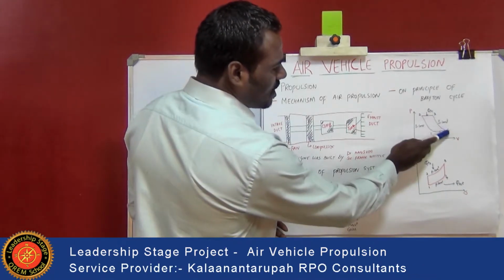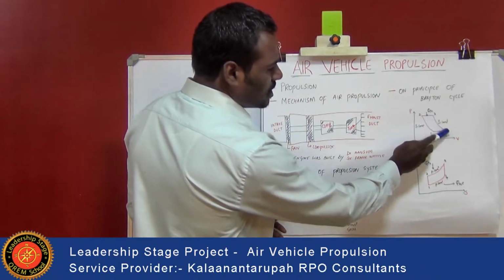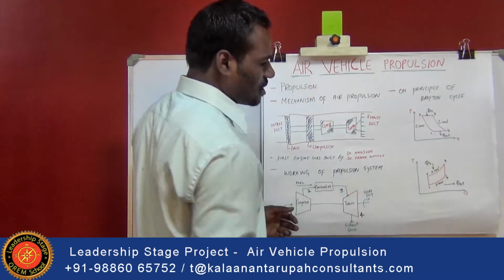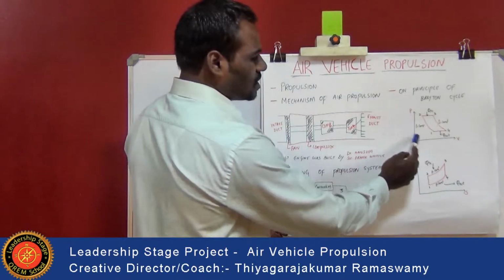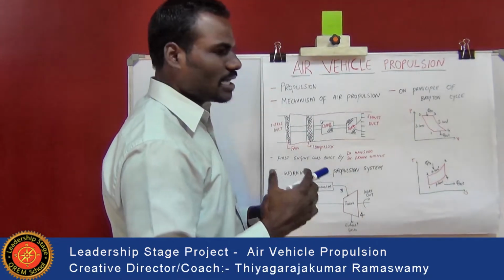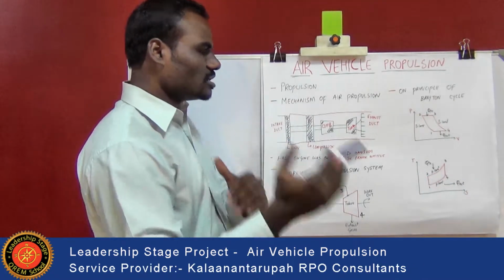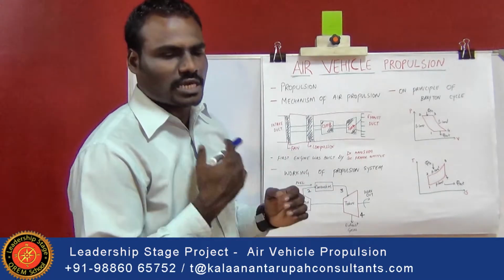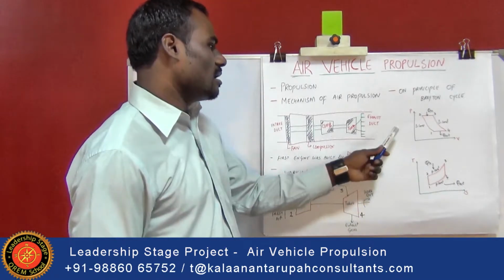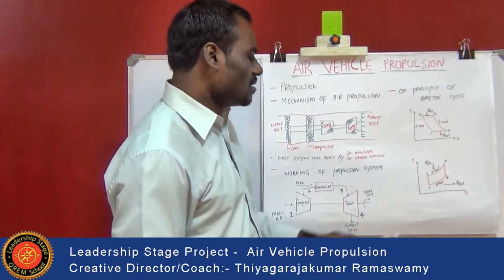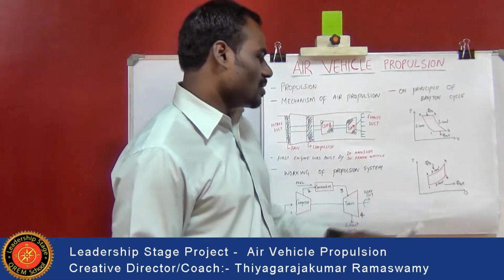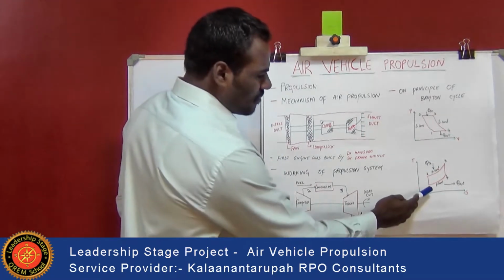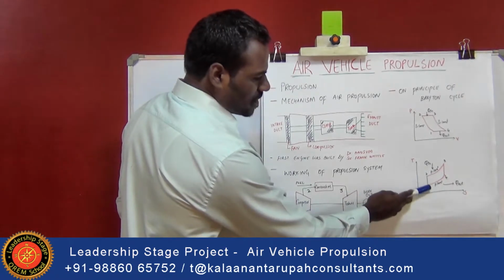Here the cycle from 3 to 4 represents a gradual decrease in the pressure of the airflow, and in the final stage from 4 to 1 a constant pressure is maintained. So how the pressure and the volume of the air change, from the inlet to the exhaust system, follows the PV diagram. And with respect to the temperature and entropy, we are calculating how the temperature drop is carried out. Here from stage 1 to 2 there is a constant temperature.